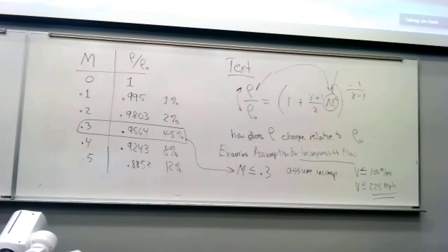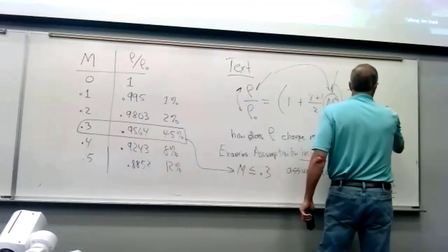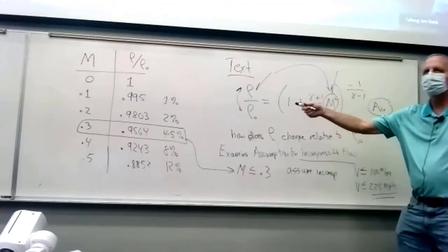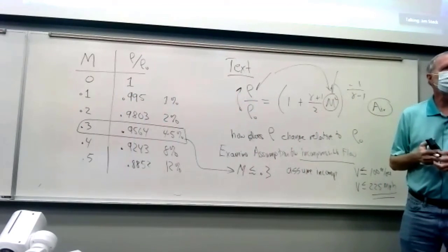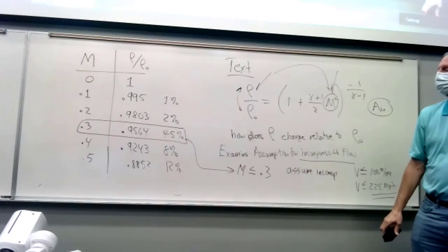Oh, yeah. And if you want to be 100% accurate, you should use the compressible flow equations all the time. But they're a pain. So if you want to get within 1% accuracy for low speed flow, you can use Bernoulli's equation and the conservation of mass equation. Or if you're doing water, now remember this is for air, because we put in gamma for air. If we're talking water, water doesn't compress unless you have really high pressure, so it's incompressible all the time. Almost, approximately.